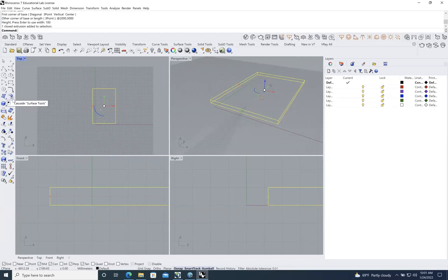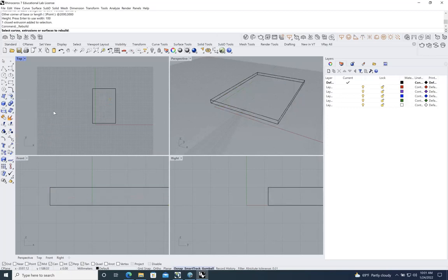And I'm going to rebuild the surface. But you probably don't know, if I rebuild the surface, I click on it and select the thing, it doesn't select. What happened is this is something called the solid. This is like a solid object. It's not a surface. So I escaped that, it failed.